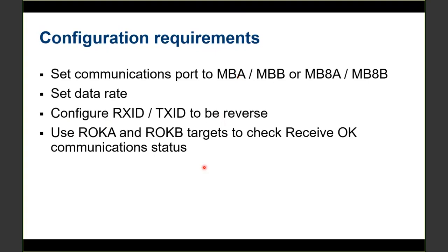And additionally, we can use other protocols such as DNP, Modbus, or SEL protocol to send this information to the SCADA system, because mirror bits is a protocol provided for protection schemes. So it's really important to monitor these word bits at the SCADA system.